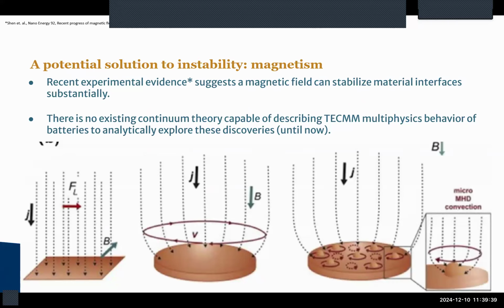Basically, if you've got imperfections at the surface, normally what happens is you get these massive current concentrations at the tip of these dendrite materials, or dendrites in these materials. So those are just growths at the tip of the, or the surface of a material, where you see current concentrations, and it's sort of a vicious cycle where you have current concentrations, it grows the dendrites, makes even more extreme current concentrations, and eventually you have a sort of short circuit. What happens with these magnetic fields, this is what they postulate currently, and what they see sort of backs it up as what is happening in the material.